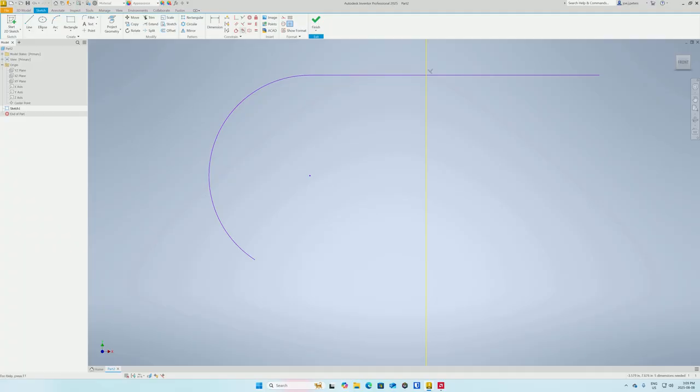Okay, so I'm not going to go through this one. This one has to do with smooth curves and splines, and we haven't used splines yet. There is also lock, which you could say lock that point down. So that just constrains all degrees of freedom of that point. I don't like using lock very much.